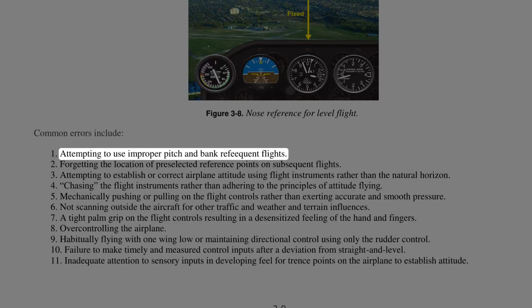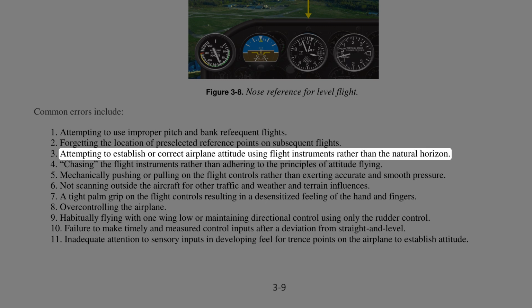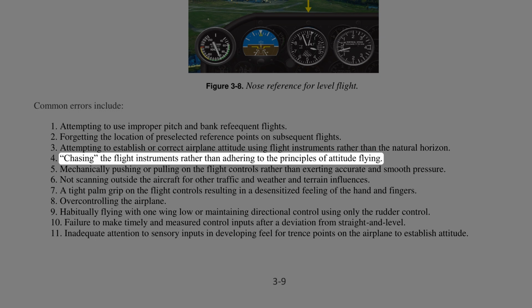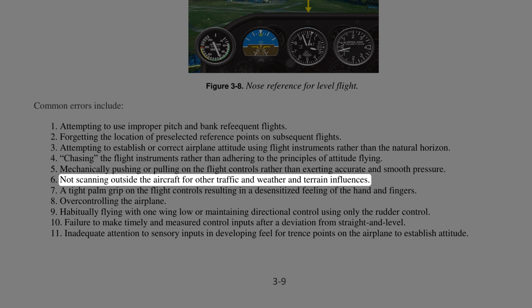Common errors include attempting to use improper pitch and bank references, forgetting the location of pre-selected reference points on subsequent flights, attempting to establish or correct airplane attitude using flight instruments rather than the natural horizon, chasing the flight instruments rather than adhering to the principles of attitude flying, mechanically pushing or pulling on the flight controls rather than exerting accurate and smooth pressure, not scanning outside the aircraft for other traffic and weather and terrain influences,